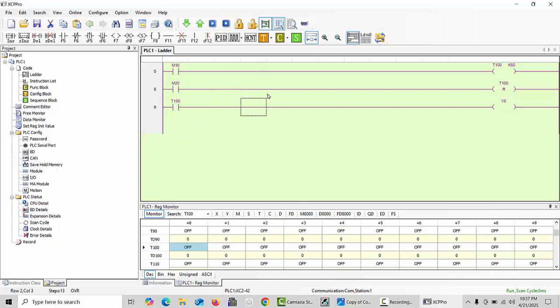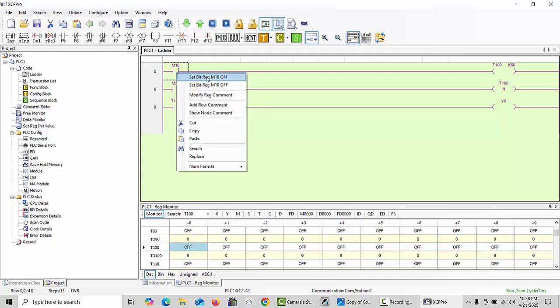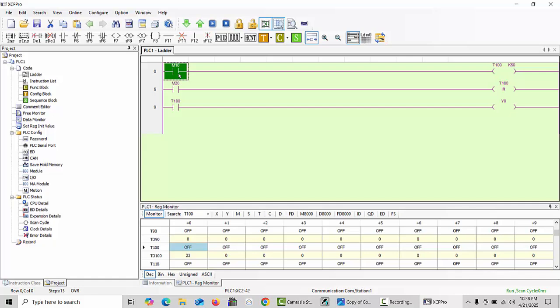This is how it is used. For example, if you set a timer for one conveyor, it will run continuously, and when the time is completed, it will stop. But if the signal does not come, it is not reset, and you need the signal. You can use a push button, a limit switch, or a sensor here. After that your timer will be reset, otherwise it will not leave its value and also not go to reset.